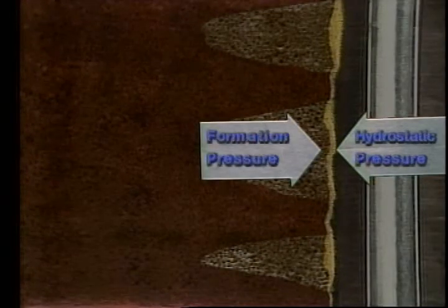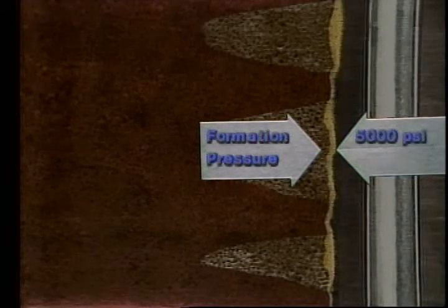It's caused by differential pressure, or the difference between the hydrostatic pressure of the mud and the formation pressure. Just as an example, we'll say we've got 5,000 psi here and 4,500 psi of formation pressure. This 500 psi overbalance causes the mud to want to migrate into the formation, and if the formation has permeability and porosity, if it leaks, an excessive wall cake will build up.